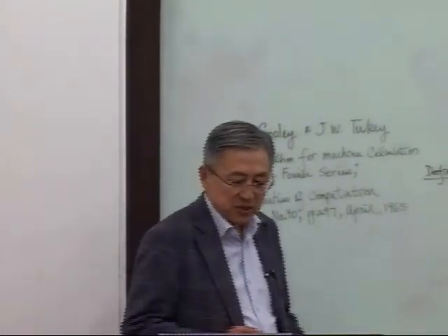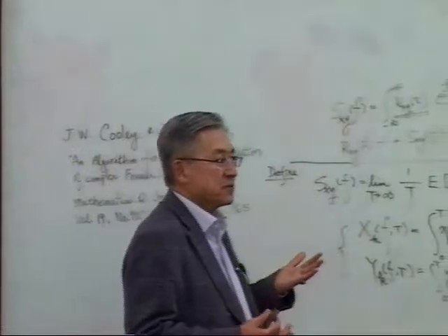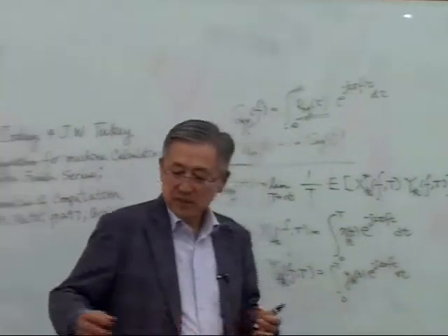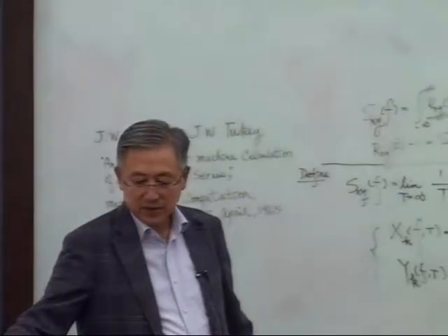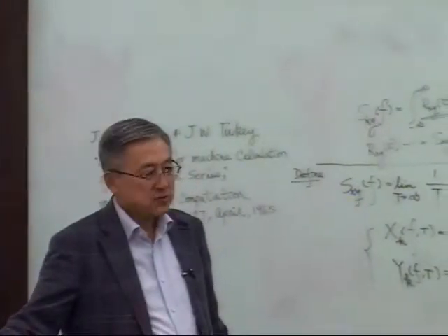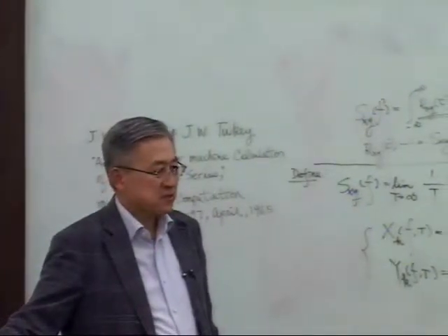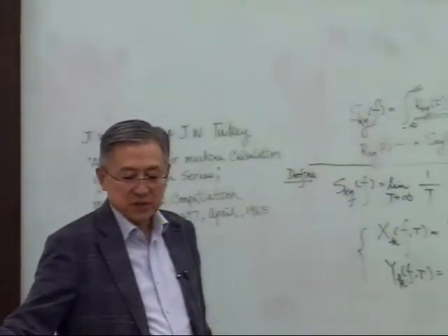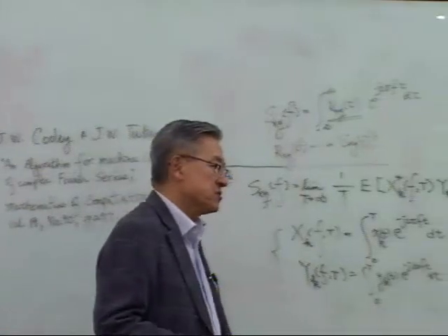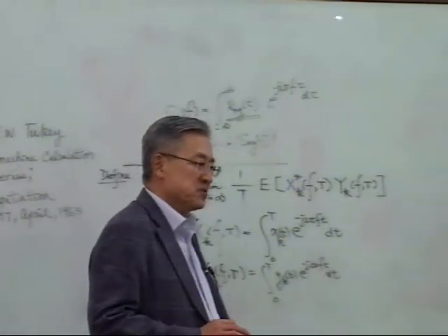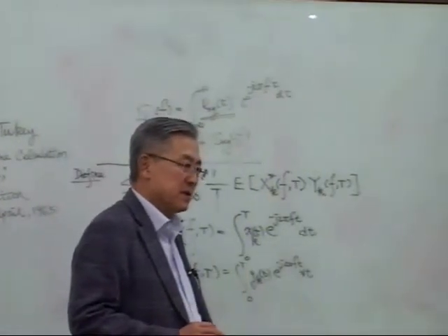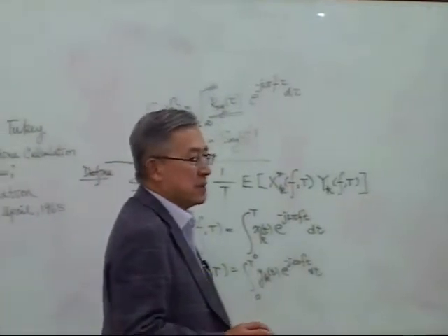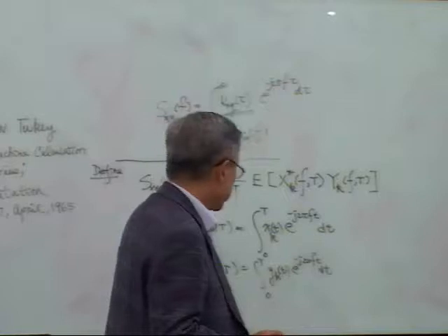Then Gxy, what's the difference? Gxy is one-sided spectra. Here, before here, this is a two-sided spectra, Sxy. And the one-sided spectra, the frequency range start from the 0. Okay? So, which means you have to double up the amplitude.